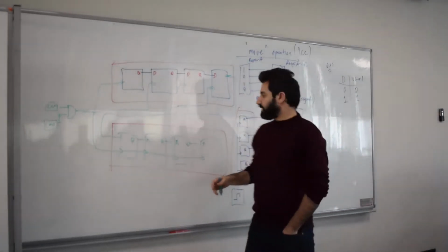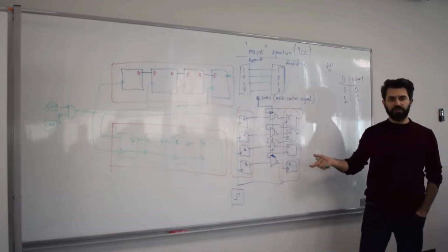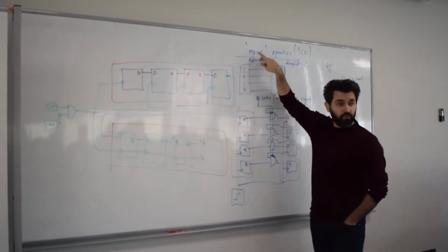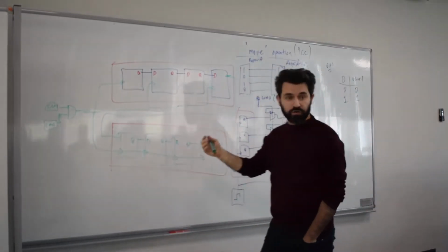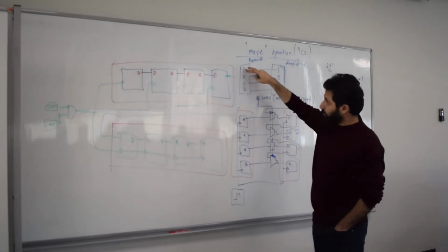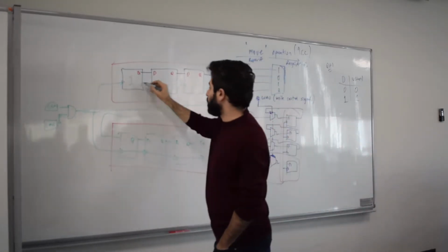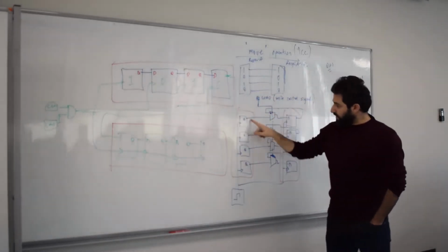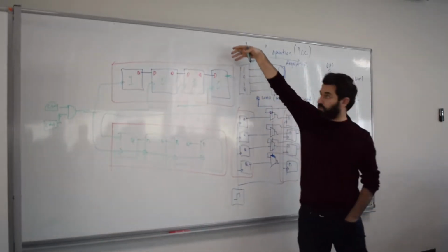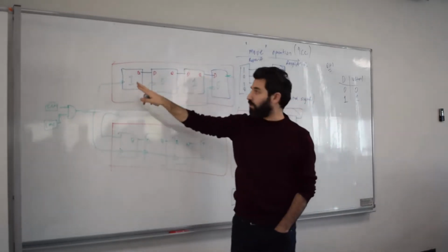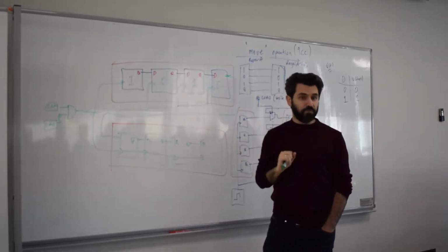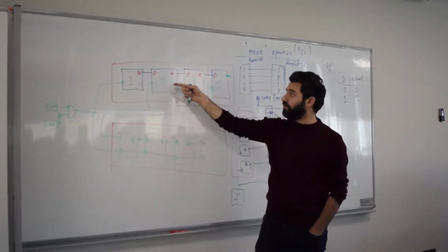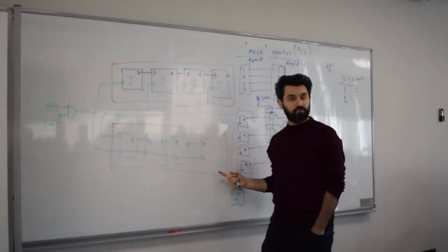So, as I said, unlike the parallel version, this serial version requires multiple cycles to do the copy operation, move operation. Okay, so let's just go through it. I'm going to assume the same thing. I'm going to have 1010 stored initially. Okay, you could actually connect these 4 to another 4 using a parallel version so that you can copy information in one clock cycle to these flip-flops directly. Then you run this shift register to shift this information to these 4 flip-flops.